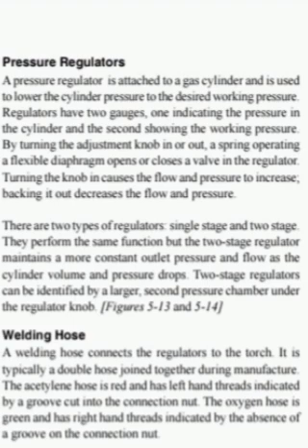There are two types of regulators, single and two-stage. They perform the same function, but the two-stage regulator maintains a more constant outlet pressure and flow as the cylinder volume and pressure drops. Two-stage regulators can be identified by a larger second pressure chamber under the regulator knob.